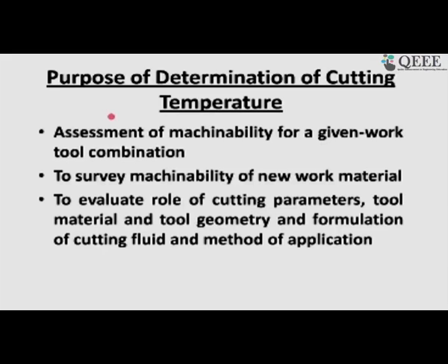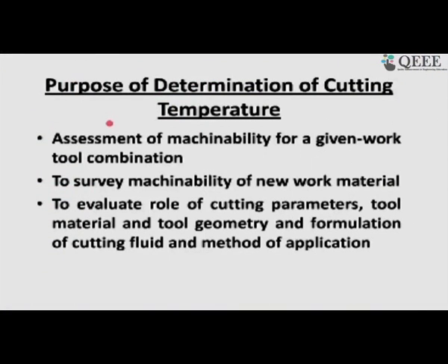So, this is one thing, and from the tool geometry point of view, friend, this is also very important, that when we talk about the temperature effect on cutting tool, it is the material of the tool, but also the geometry of the tool, means your clearance angle, rake angle, nose radius, and these are the three things which can, if we make an intelligent way of selecting those, definitely we can manage the situation with great success and the tool can perform to your satisfaction, but provided you know the effect of this geometry in controlling the cutting temperature, which geometry increases the cutting temperature, which geometrical feature can reduce the cutting temperature, all this thing an in-depth study becomes very significant. And then obviously cutting fluid and cutting method of application.